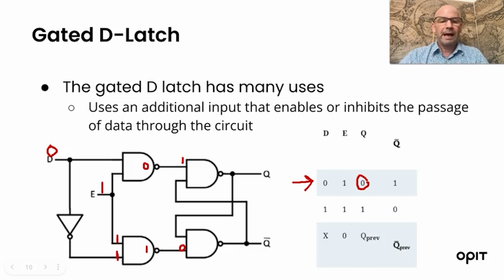Okay. Now, if we pass this logic here, we know that if this is a 0, the output is going to be a 1, right? Because it doesn't matter what this particular input is, the result will be 0 and inverted will be 1. So we know then that the value passed from here up to this AND gate makes it a 1 and a 1, which makes it an AND 1. Inverted makes it a 0.